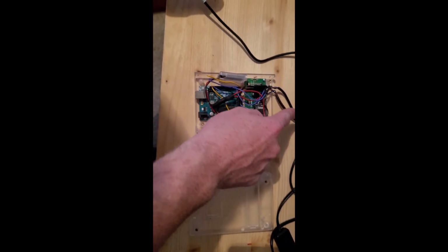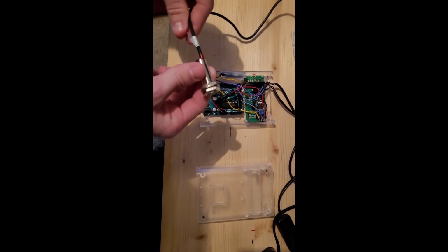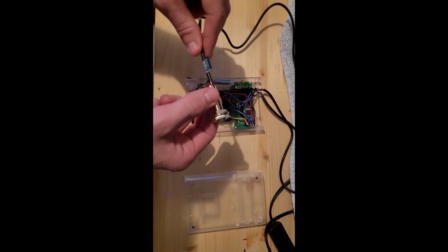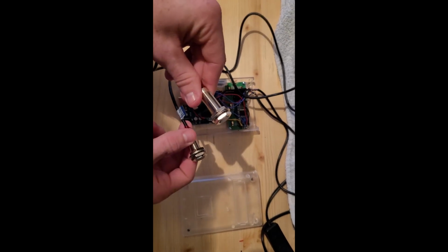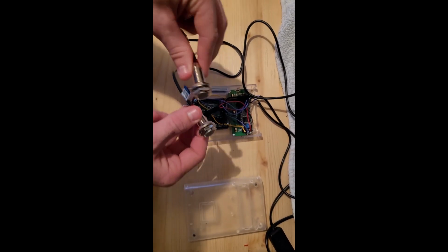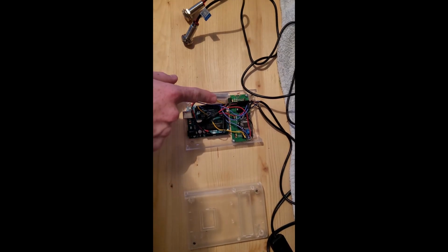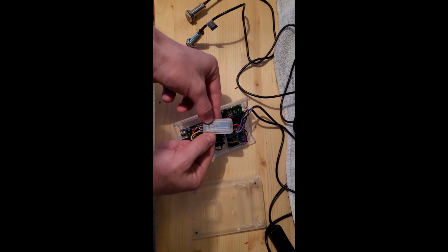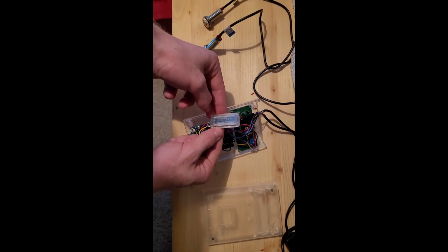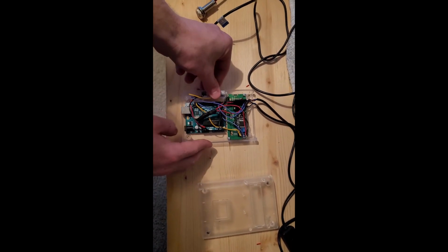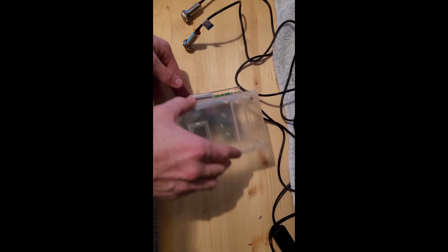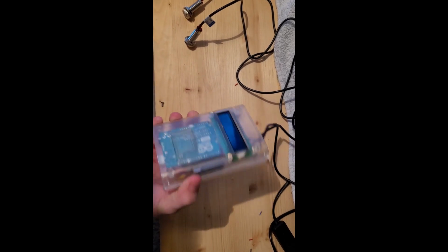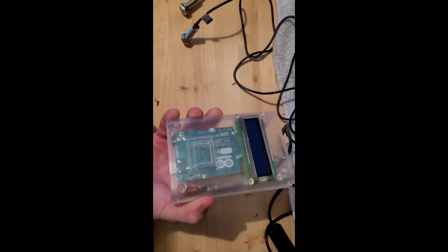After that, you can see that our wires coming out of the device are to 2 Hall effect sensors. These Hall effect sensors will link up with magnets on the cable pulling spool and track the amount of revolutions. This device right here is the Bluetooth chip so that we can transfer the data to Excel so that Excel can do all of our calculations for us. It's a very small and compact device that will make it really easy for the crews to use in the field and not get in the way.